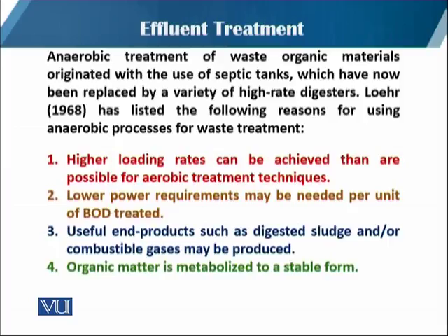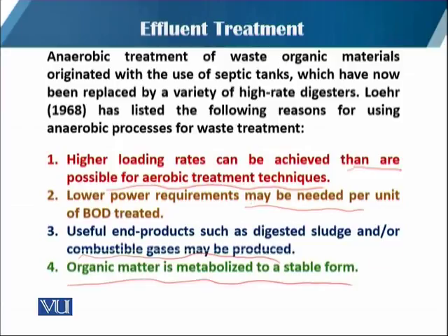Number 1, a high loading rate can be achieved, higher than is possible for aerobic treatment techniques. Number 2, lower power requirement may be needed per unit BOD treated. Number 3, useful end products such as digested sludge or combustible gases may be produced, that may be methane or hydrogen. Number 4, organic matter is metabolized to a stable form.